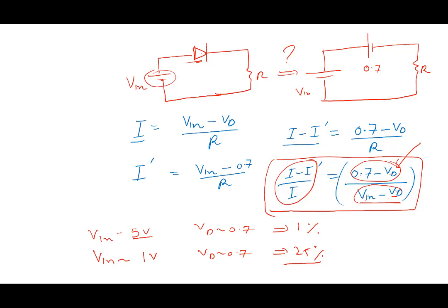In fact, why talk about Vd equal to 0.7? In many cases we use the diode with a power supply, for rectification and all that. The voltage is of the order of input voltages, 200 volt, 220 volt, right? So 200 volts, let's say. Such a high voltage here. In that case, maybe, why even 0.7? Maybe I can assume Vd equal to 0.